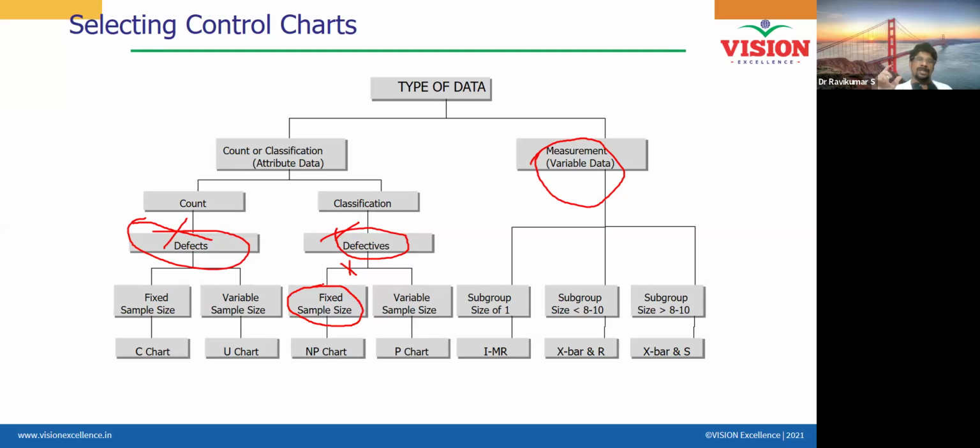Suppose you are going to select samples and write a report like rejected or unaccepted, then it is a defective chart you have to choose. Even if you collect the same number of samples every time, say every 1 hour, and write a report whether the sample is accepted or rejected, it will be considered a defective chart, because you are working on defectives. You are not working on errors or faults. Your job is to either accept or reject the lot or that component.